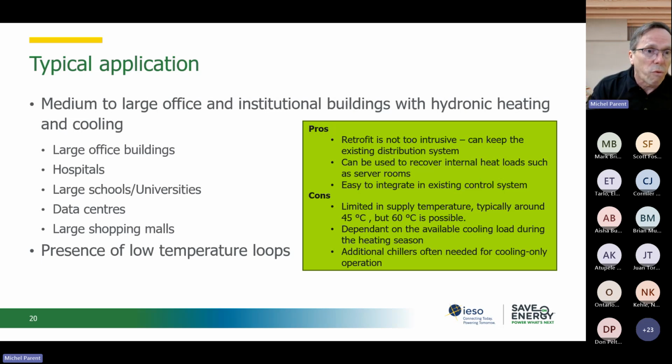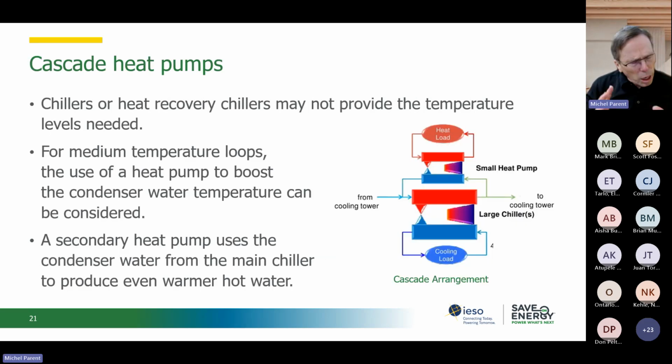So when you have a heat recovery chiller, you have to stop using free cooling for all the systems that are connected to that chiller, because you want to load up the chiller, even in the winter, with the highest possible cooling load. So you recover all the heat coming back from your return air, cool it with your heat recovery chiller, and re-inject it. Obviously it's something that requires quite a bit of a change in culture in the way the operating team would run the systems.